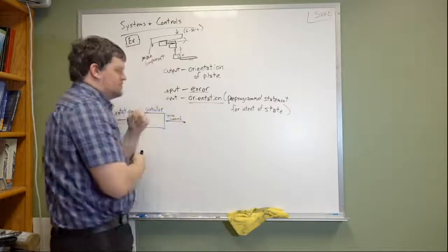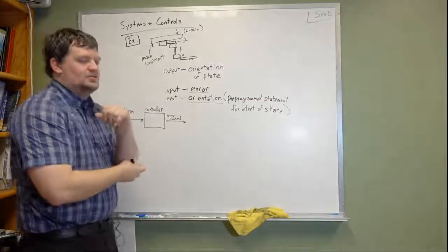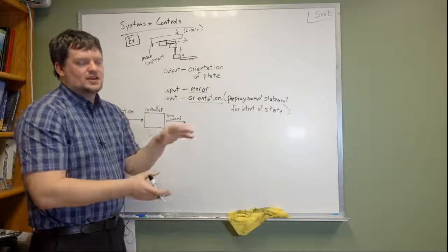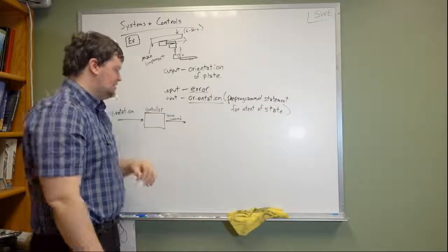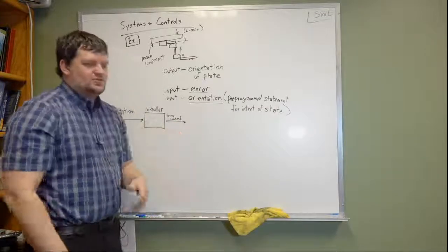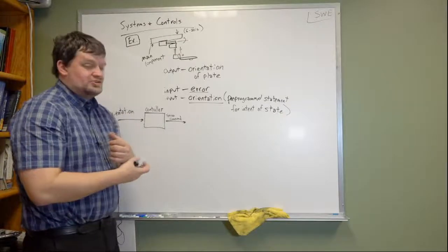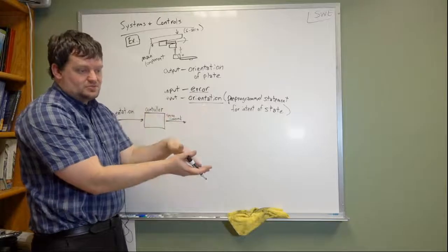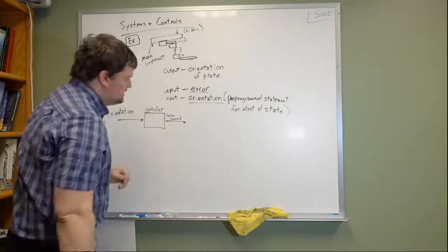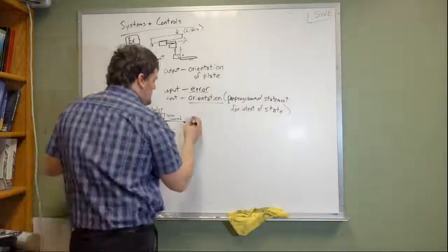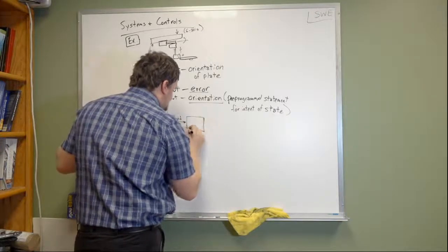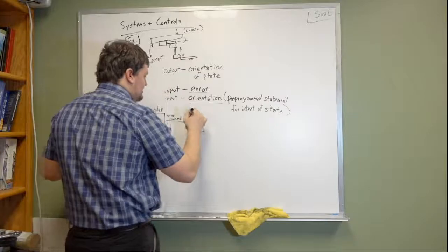Depending on the type of servo motor, it could be like, hey, I want you to be at this position. Here's a series of ones and zeros identifying the position that I want you to be at. Some servo commands are actually just analog signals, relative to maximum, go this far. So you could have a command, and what that does is it goes into a motor controller.